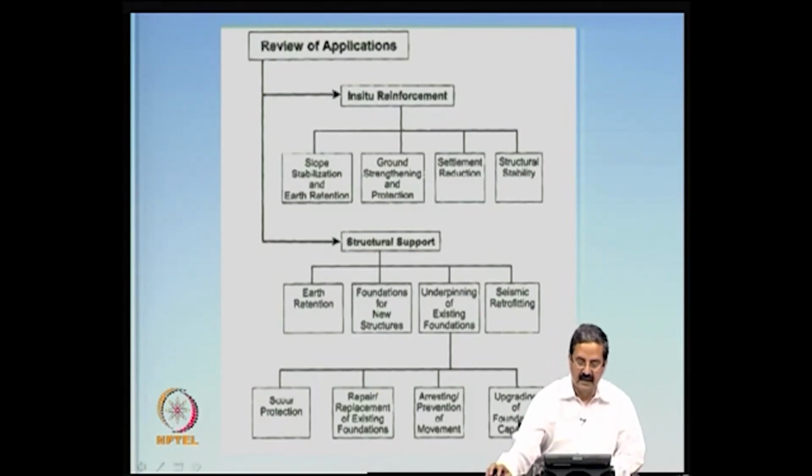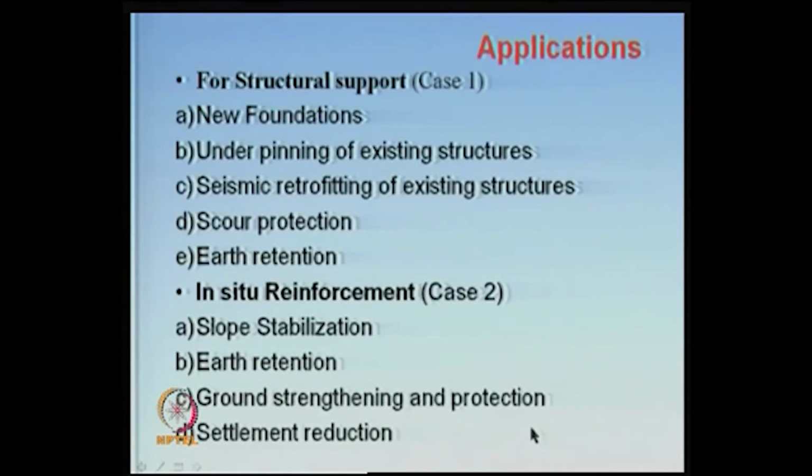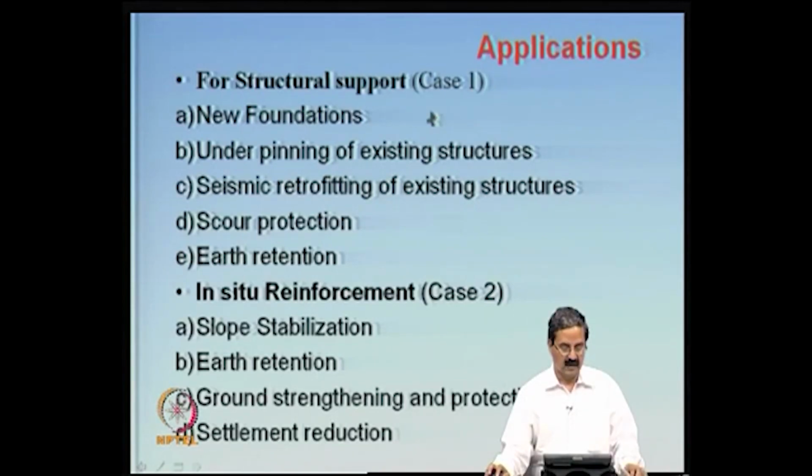Then it can also be used particularly in underpinning of existing structures, scour protection, repair and replacement of existing foundations, arresting of movement, and upgradation of foundation bearing capacity. These are some of the applications one can think of, right from new foundations to underpinning of existing structures, seismic retrofitting of existing structures, scour protection, earth retention and all that.